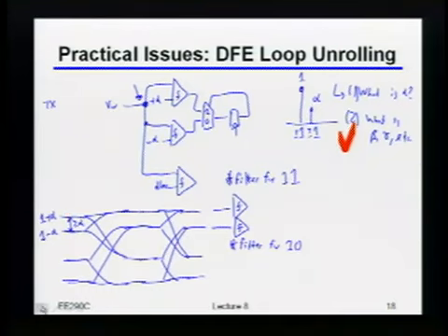I'll just give you guys one hint. Remember that for all intents and purposes, the way we're going to find those alphas is by driving some digital code into a DAC. Okay? So when I say that I want to find the difference between 1 plus alpha and 1 minus alpha, what is it that I'm actually doing? What operations do I implement in the digital domain? How do I find the difference between two things?